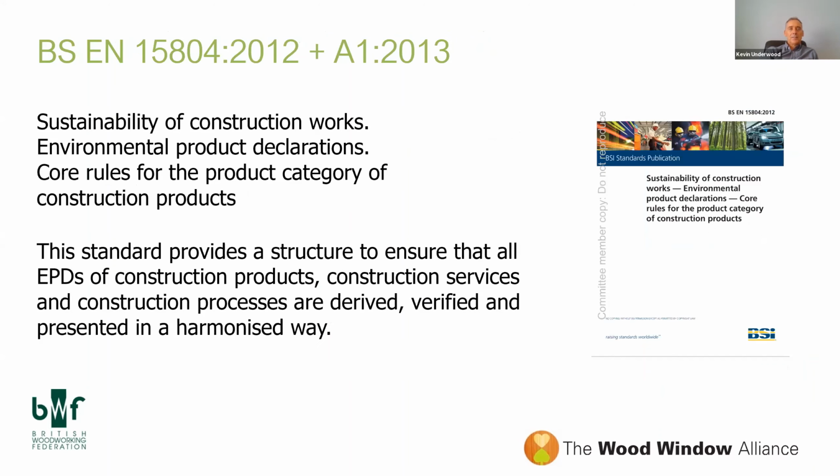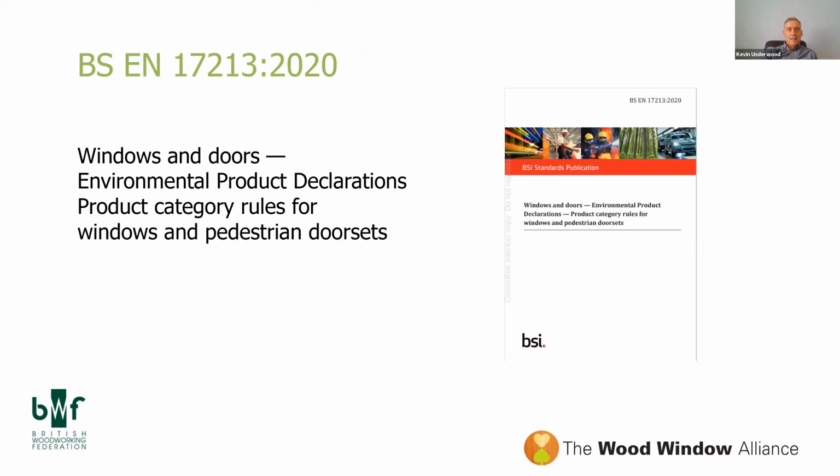So we work to the PCR in 15804. The standard provides a structure to ensure that all EPDs of construction products, construction services and construction processes are derived, verified and presented in a harmonised way. Since that was published, we now also have a PCR specifically for windows and pedestrian door sets.